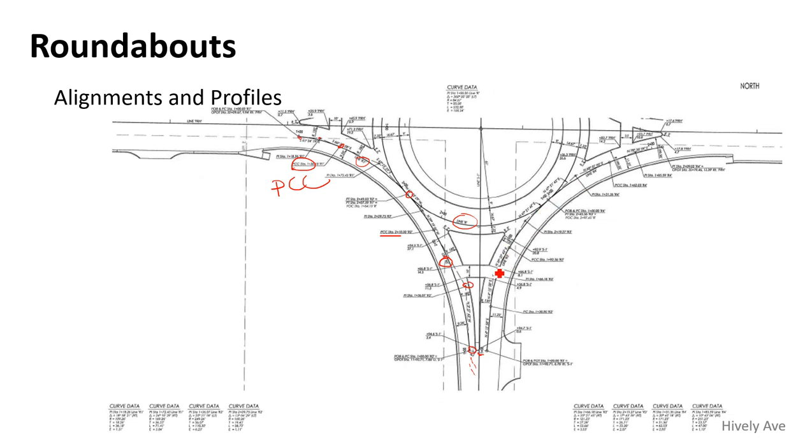Now you could probably do offsets from the center line to all these points, but contractors aren't real good at it. As complicated as this gets and as smooth as you need it to be, you're much better off designing it this way with alignments through there.